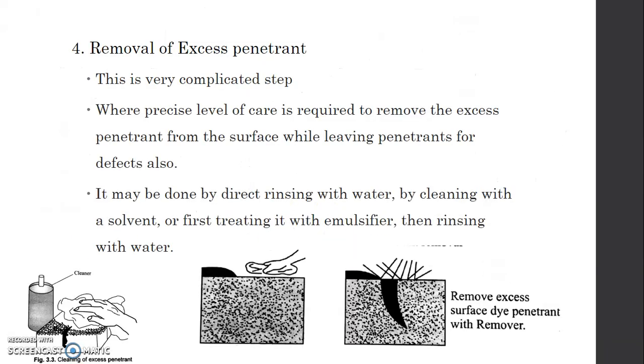The next one is removal of excess penetrant after finishing the dwell time. You have to remove all the penetrant from the surface. You can use a cloth. You have to completely clean all the penetrant from the surface, right?